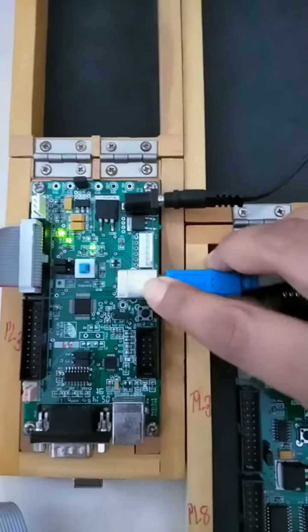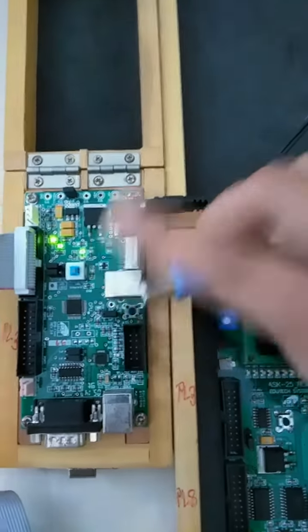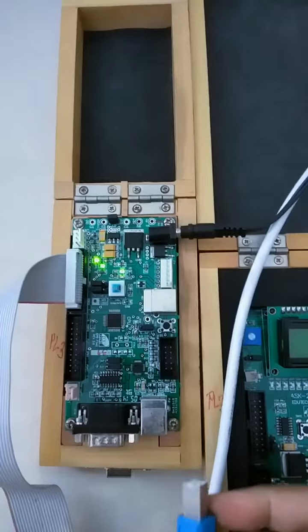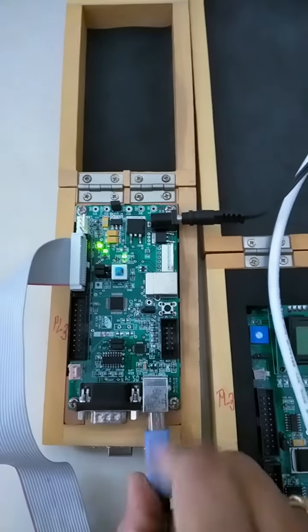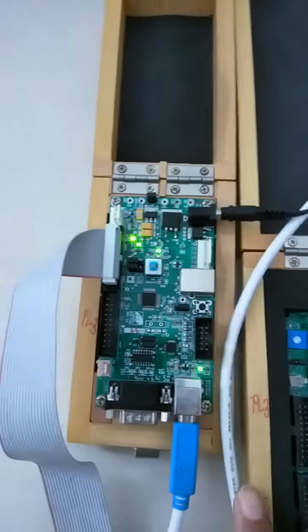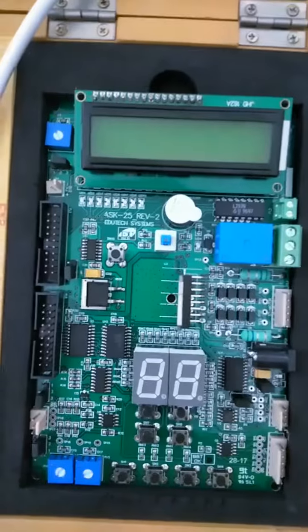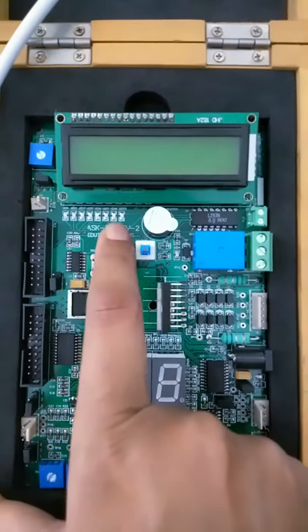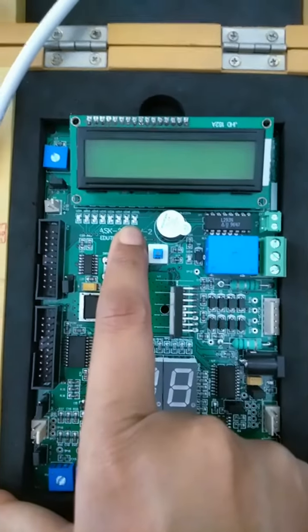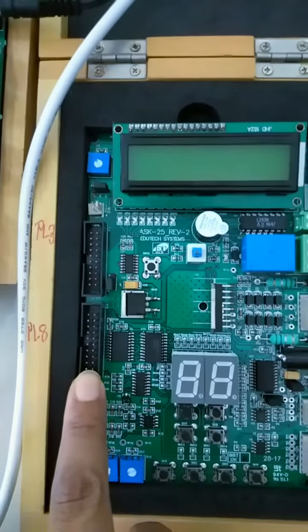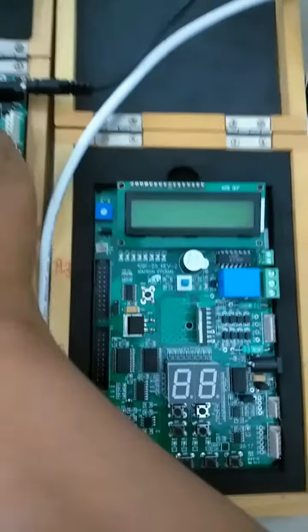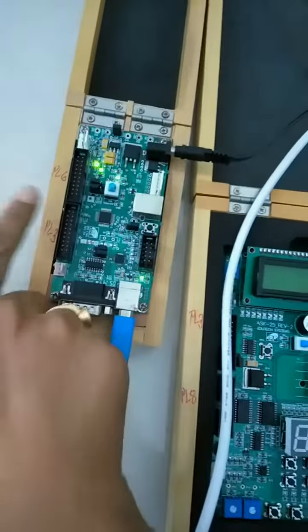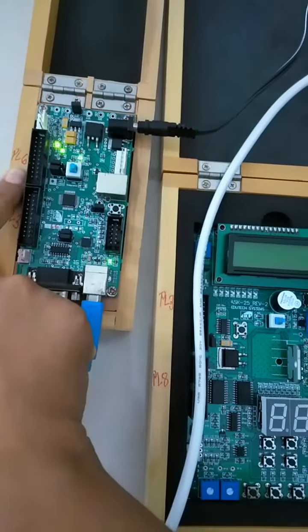The UART module should be connected. So we will use this programming cable and connect it to the UART connector over here. And also we need to observe the output on LED. So this is the peripheral board that we are having. These are the SMD packaged LEDs that we are having, and PL8 connector of this board is connected to the LEDs over here. And from the development board we are going to use this PL6 connector to connect the LEDs.